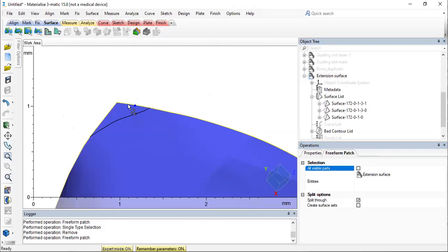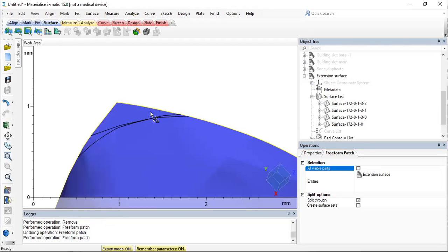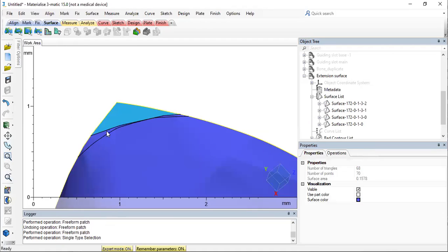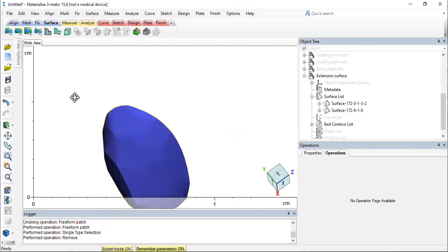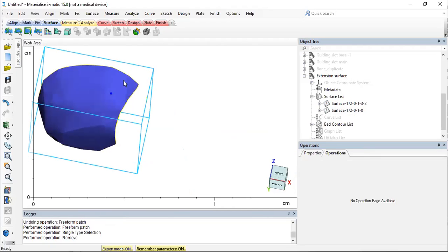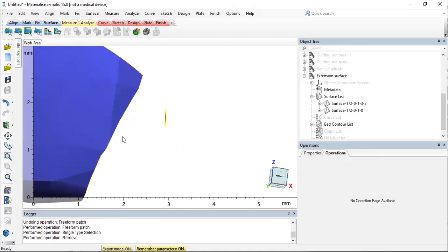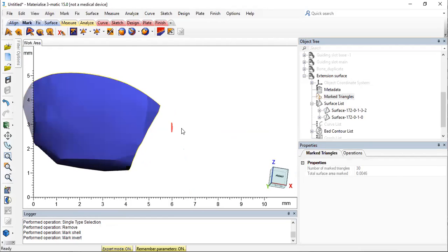Will not come correctly. Further try and smoothen it. Seems okay to me. So I'm going to filter. This seems a much rounded surface for attachment. Similarly, we're going to do that at all the edges. Try and smoothen. But what I observe is I've created a noise shell here while deleting the surface. So I'm just going to mark our main shell, invert the marking, and delete the noise shell that I'd created.